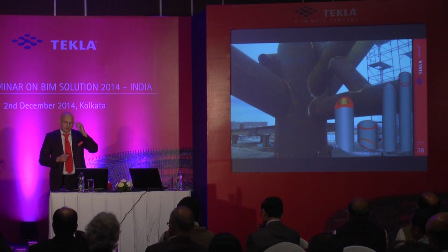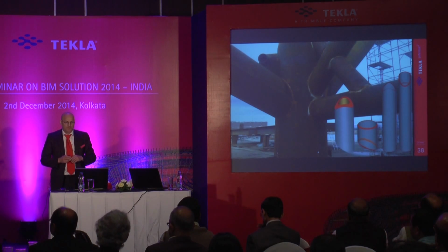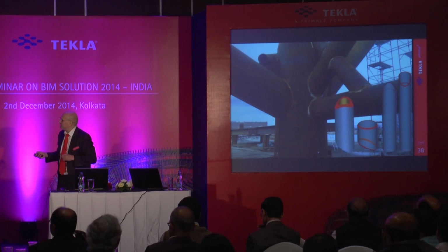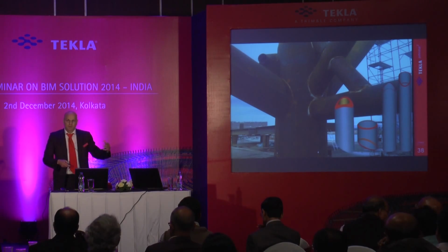It's not just for beams and angles and plates. You've also got complex pipe-to-pipe connections, especially in offshore. So we link down to specialized machines which do the three-dimensional cutting of the pipes. Beautiful machines. We put the elements in Tekla, apply the connection, and tell it what the weld preparation is, so you don't need those wraparound templates anymore that you used to create. By the way, we can still create them if you want, but you don't need them. So these are the machines. You can see what it creates. In one cut, it does the beveling and coping. So no manual preparation required whatsoever. And that's going to be a final product.